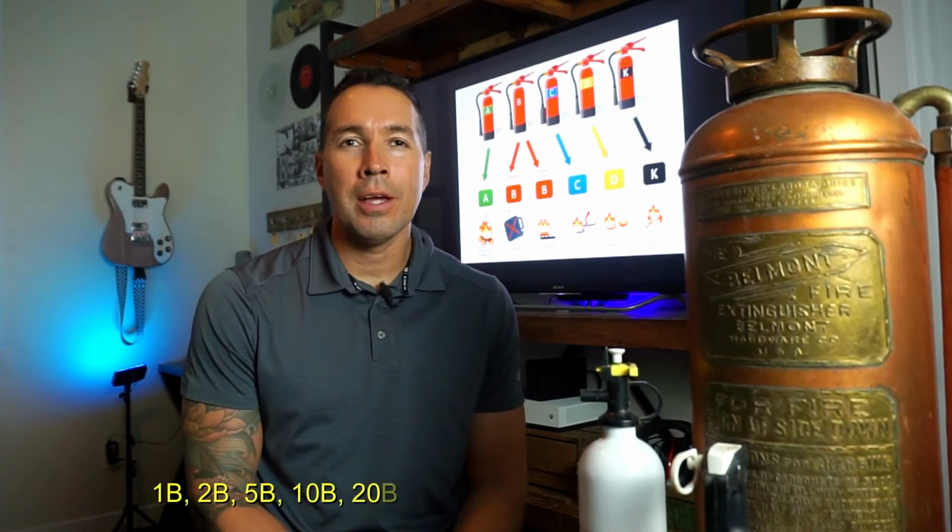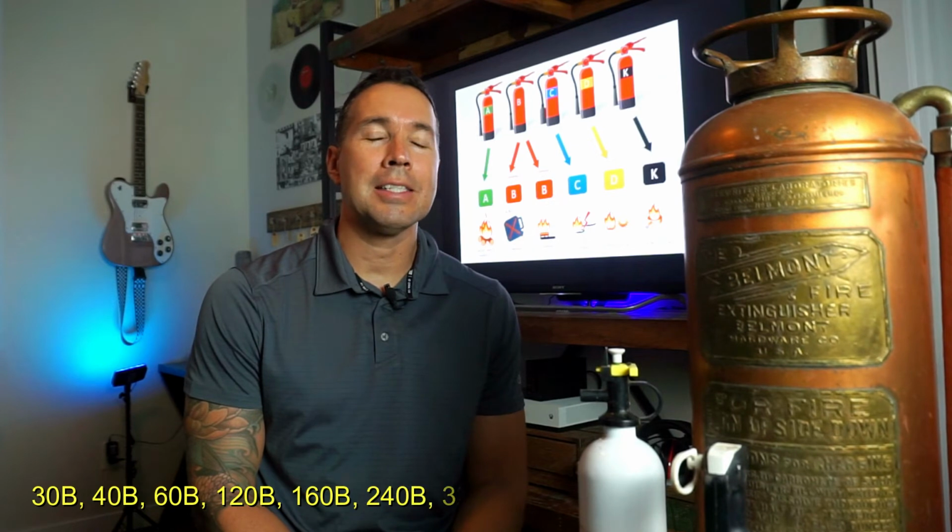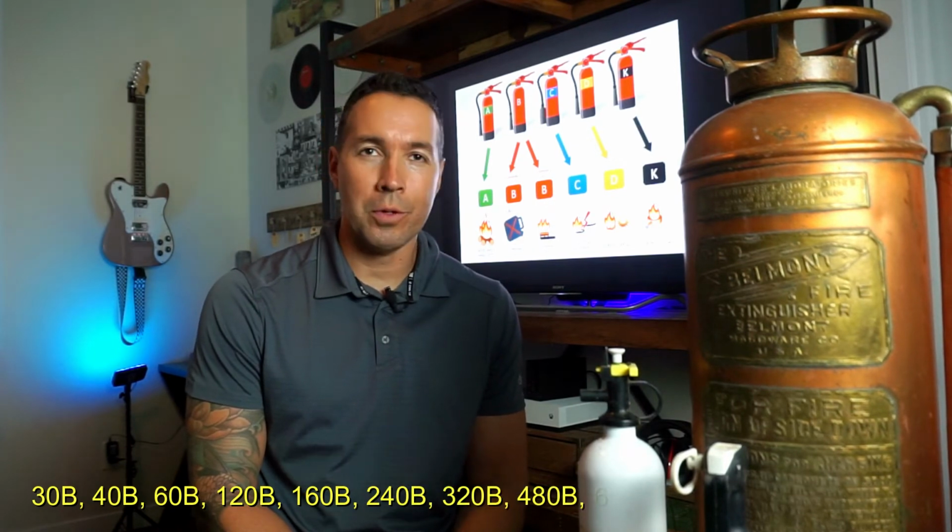Class B extinguishers also have a test rating. 1B, 2B, 5B, 10B, and 20B are for indoor. 30B, 40B, 60B, 120, 160, 240, 320, 480, and 640B are all outdoor. The Class B extinguisher number represents the square foot pan of flammable liquid it is capable of extinguishing.